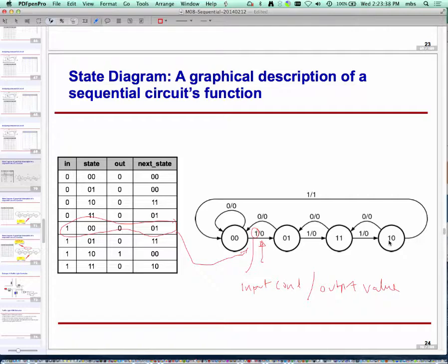So what's happening is, if the state is already 0 and my input is 0, I stay put there. If the input is 1, I increment the state by 1. If the input is 0 and I'm in any state other than 0,0, then I reduce the state count by 1. So it's an up counter, down counter, and stay put at 0 kind of thing that is happening.